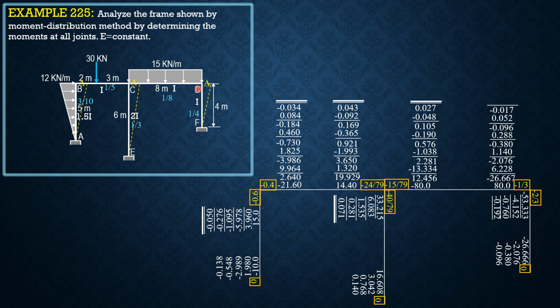Moment DF or FD is negative 6, EI is 1, delta over 4 square, L square is 4 square. So it is negative 3 delta over 8. The LCD of the denominator should be 25 times 3 times 8 or 2 cube. So that would be 600, and 600 is very large, which will make the side sway moment very high. So let's reduce that 600 to 100.